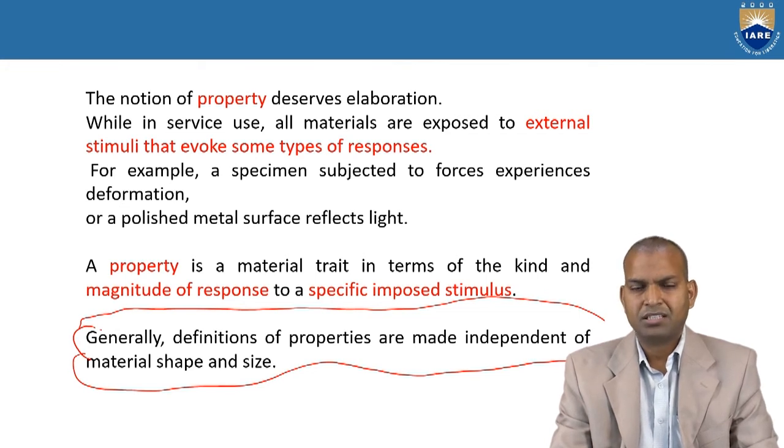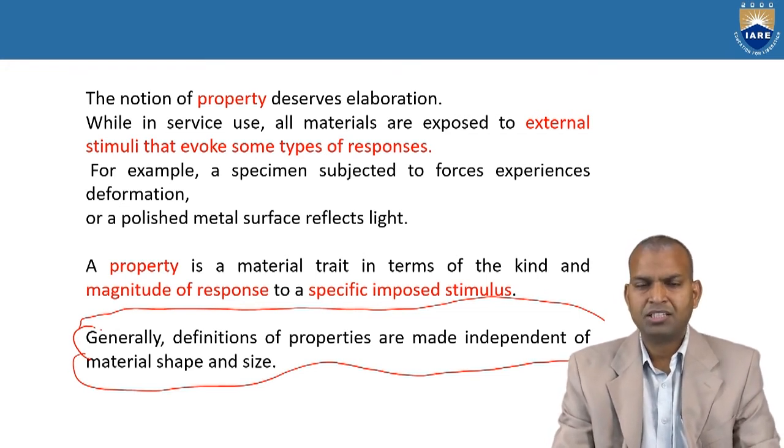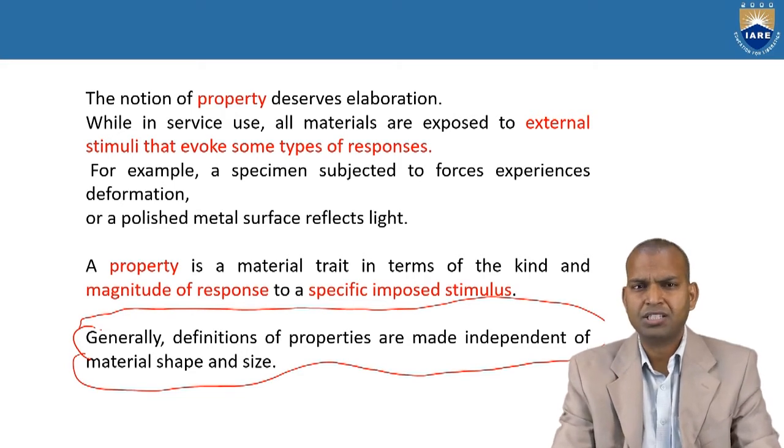If we want to find out the tensile strength of that particular material, then we have to use a universal testing machine. And if you want to find out the hardness of a certain material, then we have to go for a hardness test rig. So there are various properties, such as ductility, brittleness, hardness, malleability, and tensile strength. These are all various mechanical properties of materials.